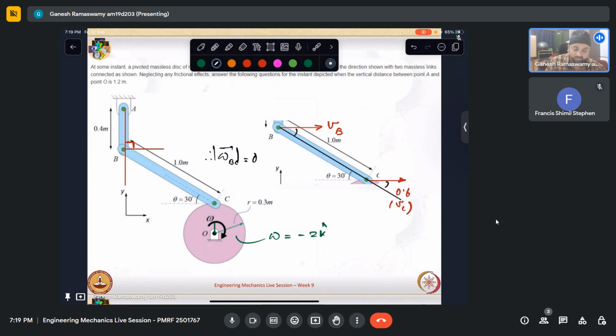Instantaneous? Yeah, exactly. We can do it by that also. If we were to draw this, these two are parallel lines which meet at infinity. Yeah, that also, exactly. We can use that. So since these two are parallel, the lines perpendicular drawn meet at infinity. So there is no rotation essentially. So it can be done with the instantaneous center of velocity also. That's a good point.